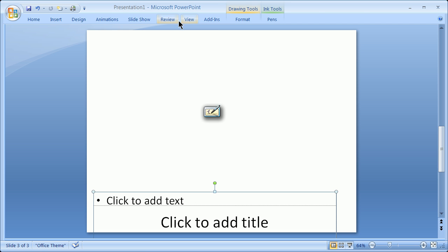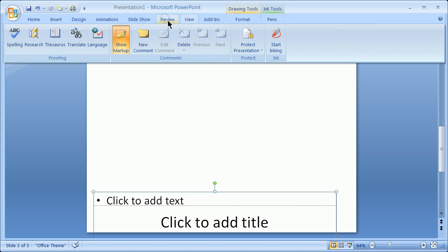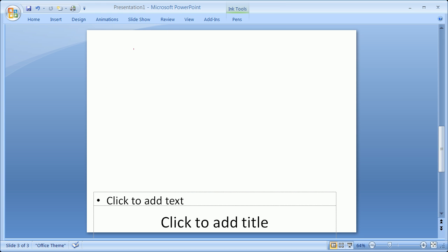The other thing you want to do is review, start inking. You want to think about the most basic system so you can process through what we talked about as velocities generally being in the order of 3 to 10 feet per second, but they can be more. And also, like it or not, the top end of your velocities is equal to the square root of 2gh. So if you have something falling a distance of 155 feet, it could achieve a velocity of 100 feet per second, or 68 miles an hour. We're usually a lot less than that. There are a lot of smaller flows than this.